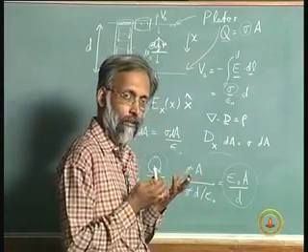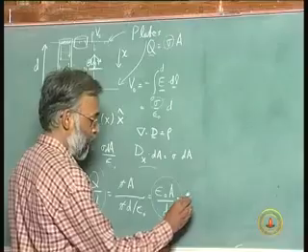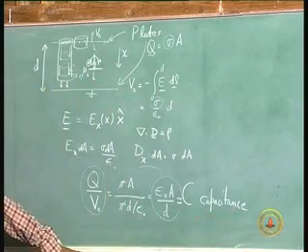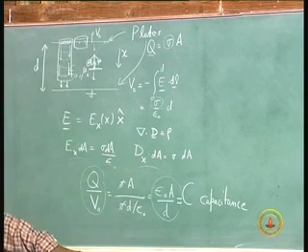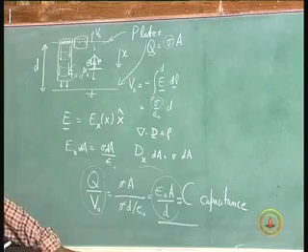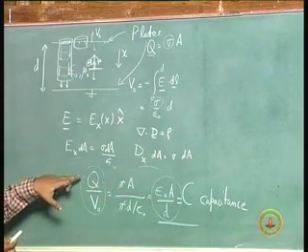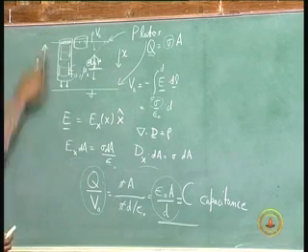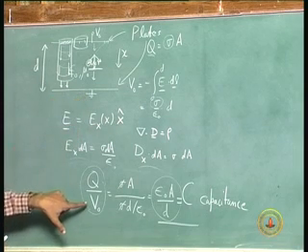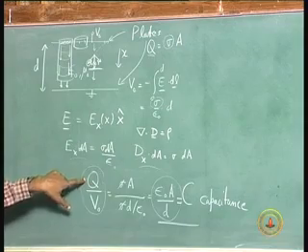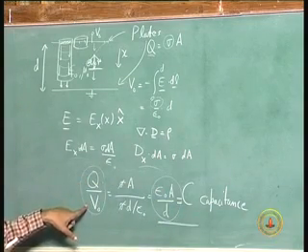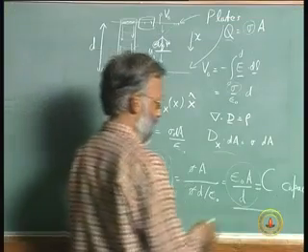And this quantity that is only a function of device parameters is called capacitance. So, this is a very important concept, and it does not hurt to repeat this as many times as possible. Capacitance is a measure of how much charge is induced on a plate when you put that plate at 1 volt with respect to the ground. So, if I set V naught to 1, then the amount of charge I will induce in coulombs will be the capacitance itself. So, the unit of capacitance should be coulombs per volt directly, but it is given a new unit, the unit is called farad.